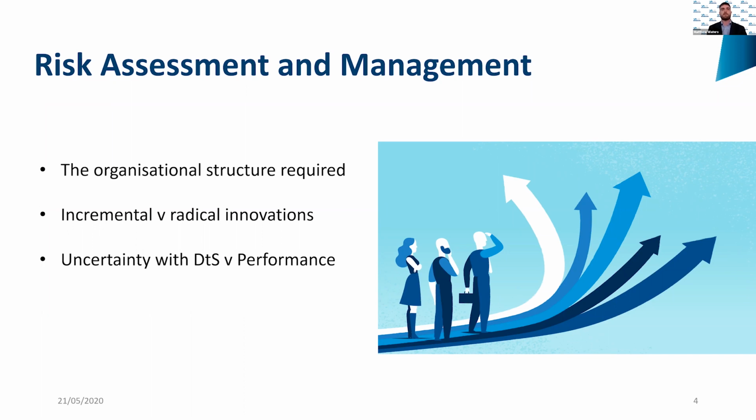Really, as deficiencies or failures or improvements are identified, what happens is the DTS provisions incrementally shift to incorporate any necessary changes to achieve the desired objectives. We can see examples of this in essentially every amendment to the BCA. There have been some recent examples of out of cycle amendments where the BCA was amended to incorporate some clarification. An example of that is 2019 NCC Amendment 1, with some clarification around timber frame concessions under Spec C1.1.